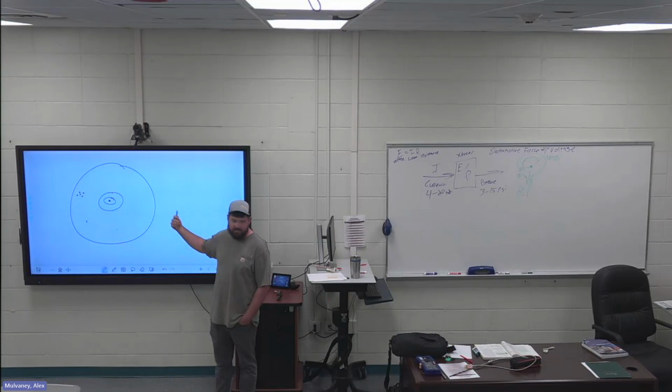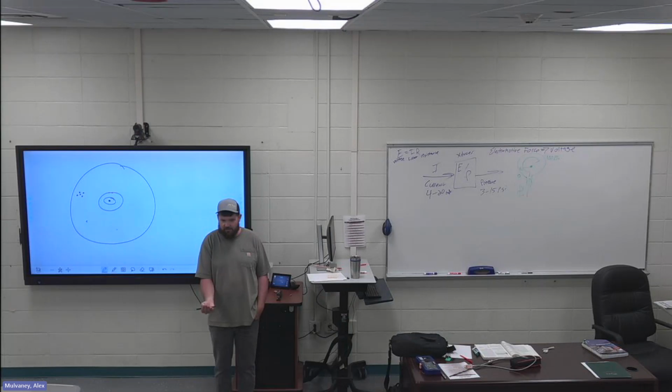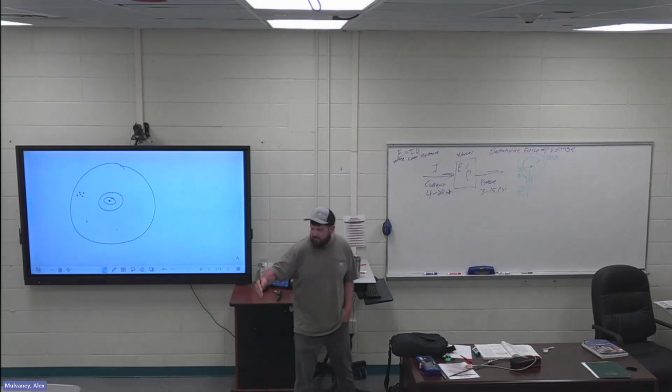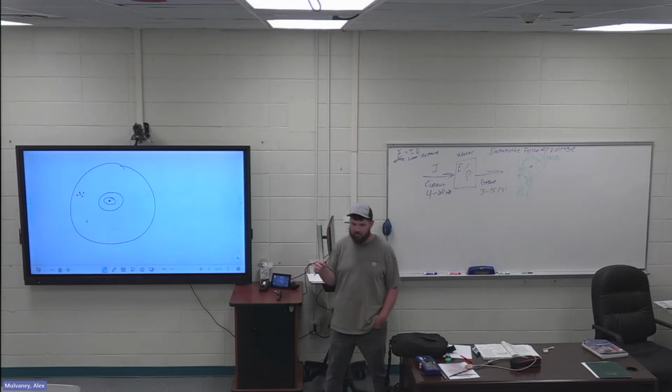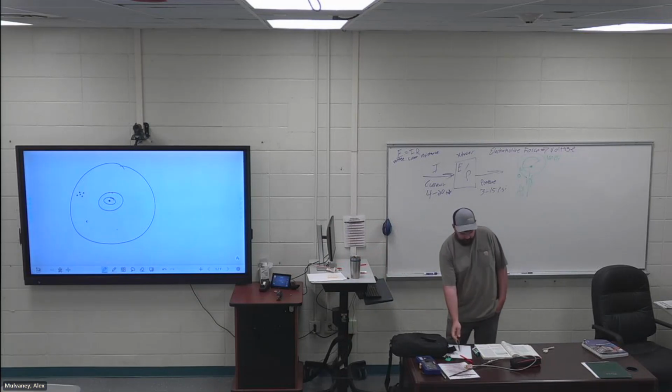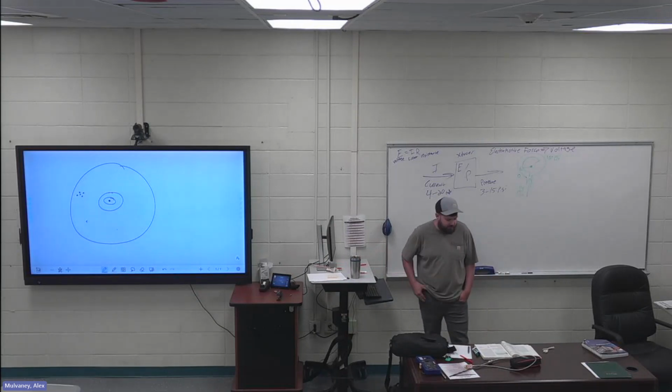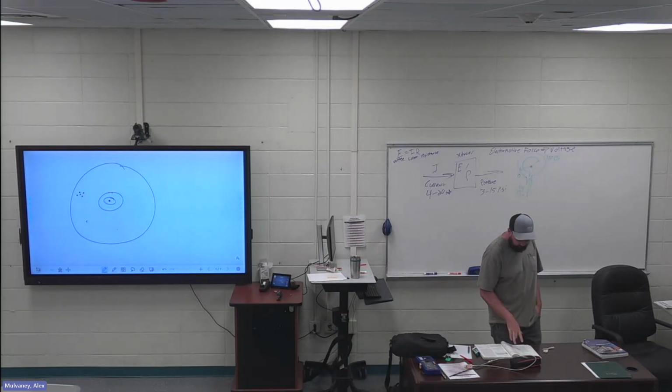Like I am constantly 5 PSI off of my super calibrated gauge that I'm reading in my hand. Well, I'm going to have to recalibrate that device. It is precise. If you have something that's not precise, then you're going to have to dig in a little bit more. Stuff like that. But you need to know the difference between accuracy and precision.